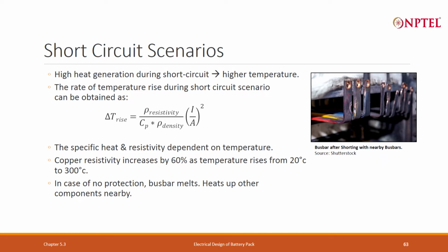But if it is happening externally, the same thing can happen internally also, within the pack. So, we should also worry about, if it is happening inside, can we put something known as a thermal fuse within the bus bar. So, what will happen? It will get disconnected quickly there. A thermal fuse also melts, but its melting point is much lower than the bus bar material melting temperature. Could be 60 degrees or 70 degrees or 100 degrees.